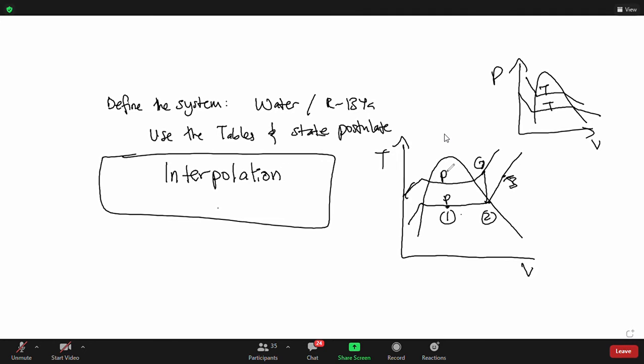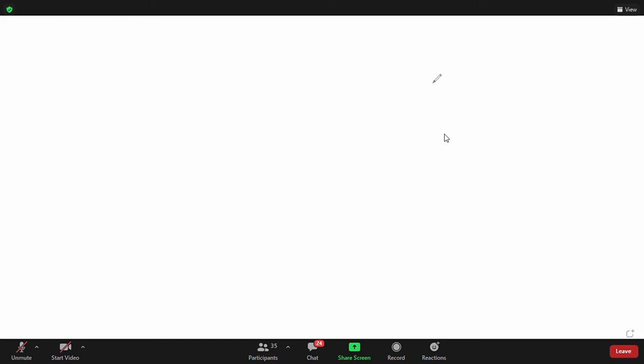You must understand how to find boundary work from the integral PdV. You understand expansion is positive, compression is negative, work in, work out. Unit, be careful if mass is not given. If the answer wants per kilogram, then the mass will not be given. So are there any questions on this? Are there any questions on the closed system, first law of closed system?